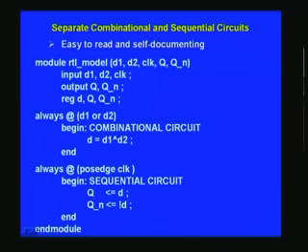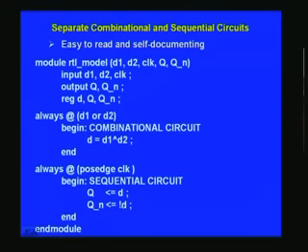So here we are inverting this D. Although we are inverting, you will actually be surprised to find two flip flops in the synthesis tool, not just one. Our intention was to make just one flip flop, and the other is merely an inversion of this, but unfortunately the tool does not have that much intelligence. If you want, you will have to circumvent it.